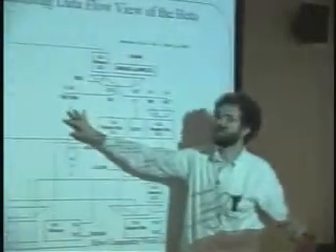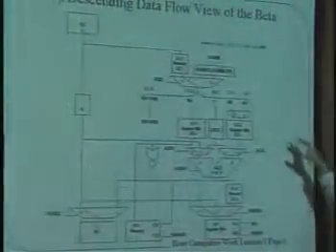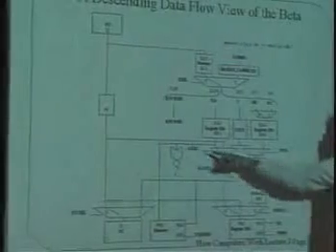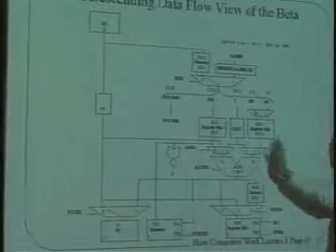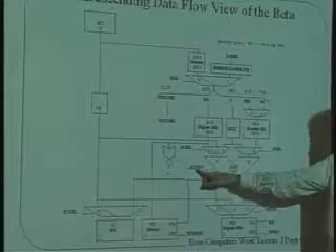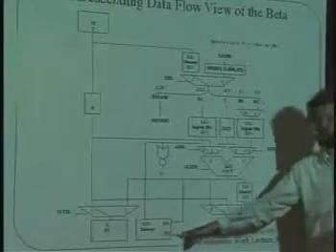So the opcode controls that? So in the end, yes, the opcode will control everything. The opcode will be decoded by some control logic on the side, and will control how each of these selectors is told what to do. It'll control the ALU function, telling the ALU what to do, and it will also control the memories down here, telling them whether or not to pay attention to the clock and to store something new.